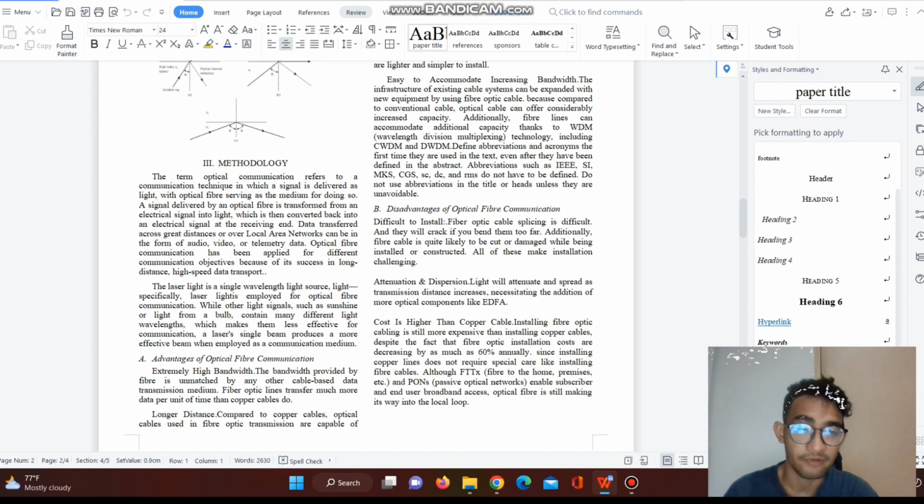The last disadvantage is that special equipment is often required. Some specialized equipment is required to guarantee the fiber optic transmission quality. For instance, expensive specialized optical test equipment like optical probes and power meters are needed at the majority of fiber endpoints. This equipment is known as OTDR, which is optical time domain reflectometry.